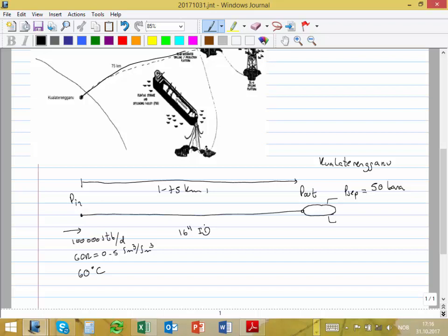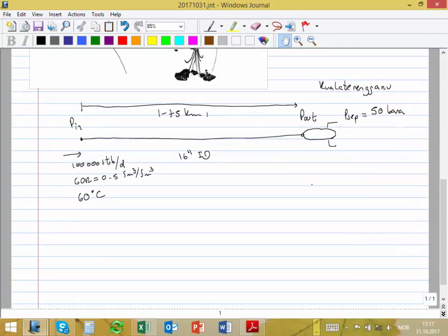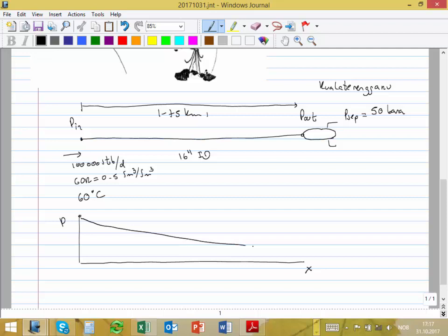So note something. What do we want? Okay, in this equation, what do we want? Do we want P1 or P2? We want P1, right? The inlet pressure, the required pressure at the inlet of the pipe. Probably when I plot the pressure versus length, the pressure here will have a value that is high, and then it will go down all the way to 50 bar, right?